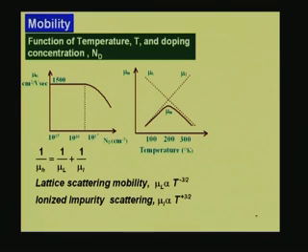So, if you can separate out the ionized impurities and these electrons, then there is no ionized impurity scattering. That means this term is not there. The entire mobility versus temperature curve will be like this, totally like this. If that is the situation, you go down to lower temperature, mobility can be high. Okay. So, this is one concept, please remember.